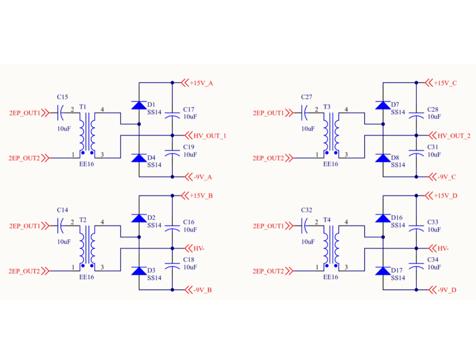By using independent isolated supplies for each gate driver channel, the design minimizes common mode noise, avoids ground loops, and ensures robust and consistent gate drive performance, even under fast dV/dt conditions.